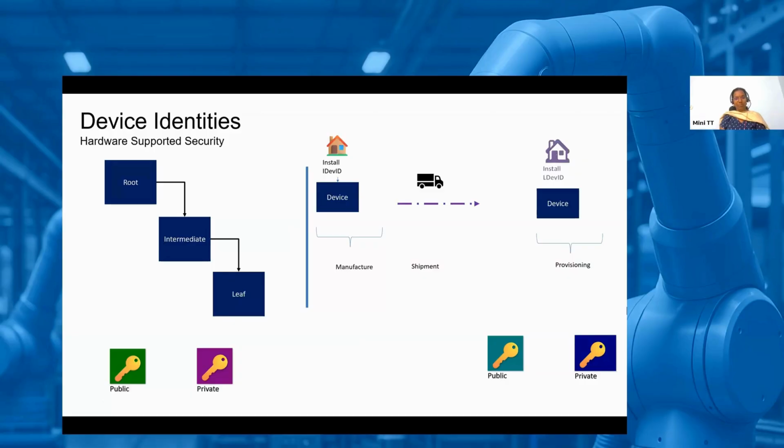So there is a private key, public key pair within every instance of the device. This is the instance specific identification, which is also traceable to the manufacturer because it is signed using the manufacturer certificate. And there is a certificate chain which is rooted on the manufacturer CA. When you are manufacturing, you install an IDevID. This is called an IDevID. Some people call it a birth certificate, an initial device identifier, a fingerprint certificate, such kinds of terms. I think DigiCert was calling it an evergreen certificate at some time. All that is put in, then you ship it.